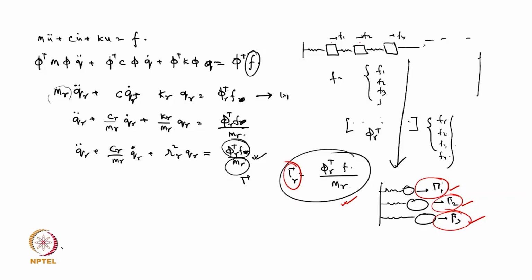The force may be applied in a 180 degree phase, so you can get positive, negative, all those things are possible. Okay, so now let's see what is that 90 or 95% clause in Indian code. That is known as the mass participation factor, not the modal participation factor. There's a very small difference, but they are different.